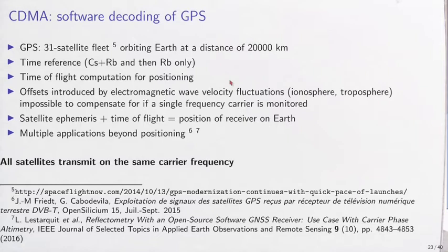position, velocity, and time when more than 4 satellites are visible from the receiver. Some offset might be introduced on the time of flight that will be the cause of the loss of some of the resolution, and indeed by addressing the GPS processing and the radio frequency layer, we have many more applications than basic positioning in addition to using these high stability clocks.